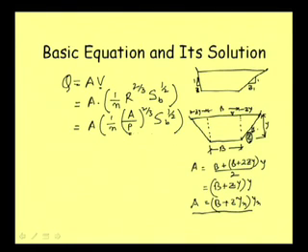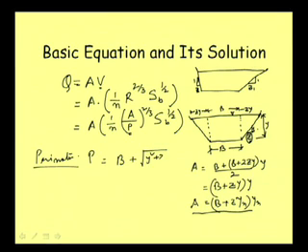Say this perimeter we can write as perimeter P. This is nothing but B plus, say, what this length is. Say this is Z y and this is y. So this inclined length will be root over y square plus z square y square, and that sort of length we have two. Here is this one and here is this one. So it is B plus this into 2.